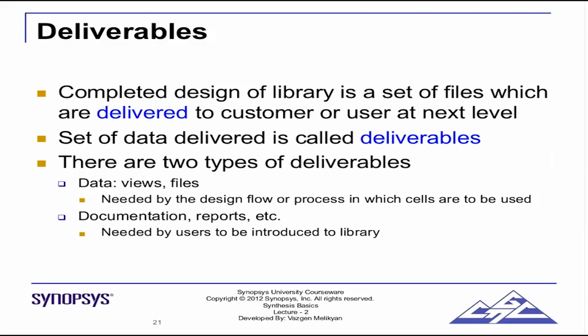Now, the library data, that is the standard cells, usually comes from some sort of vendor. It can be external, it could be internal. For example, the fabrication lab TSMC itself gives standard cell libraries which are qualified on its own fabrication process. That is an external vendor. Many companies have internal teams that develop standard cells for a particular foundry.